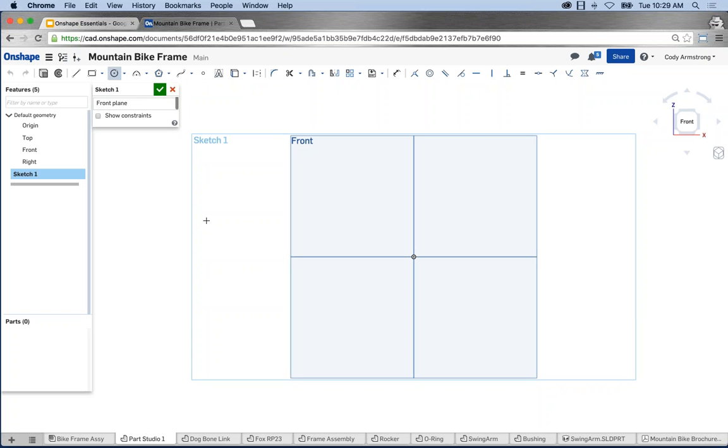As I move my cursor out and move it around the graphics here, you'll start to see these inferences of these lines get woken up. So as I move this horizontal, notice that I get the dotted pattern lines indicating that I'm creating a horizontal constraint to the origin. So you will get that attaching or snapping behavior if you've come from a traditional CAD system, very typical.